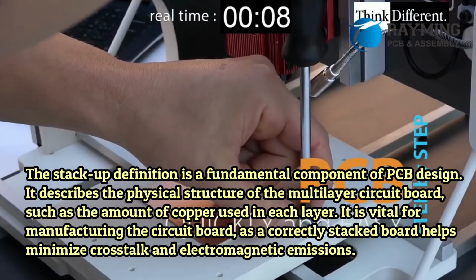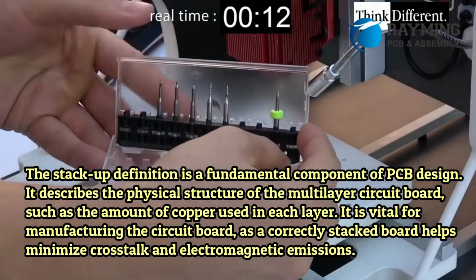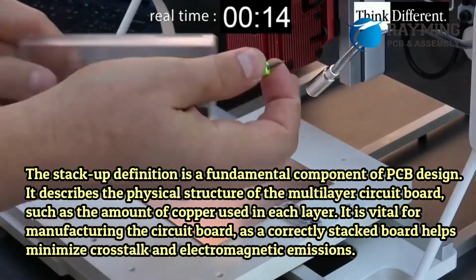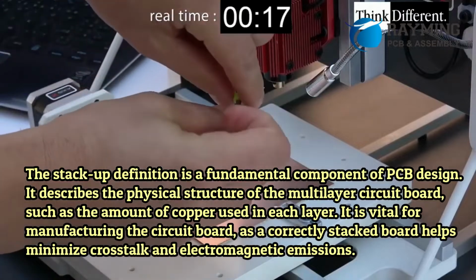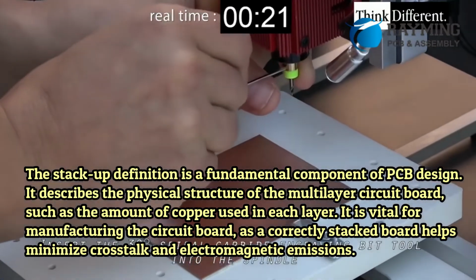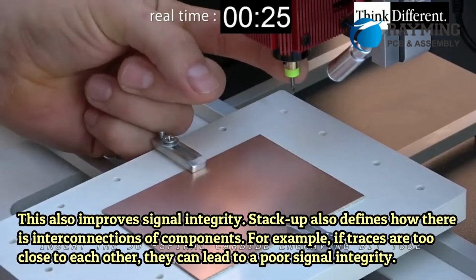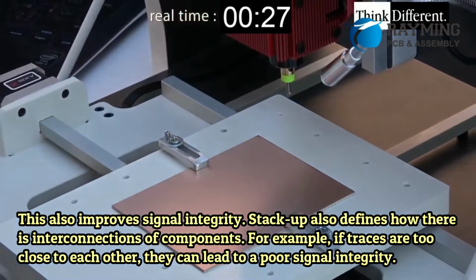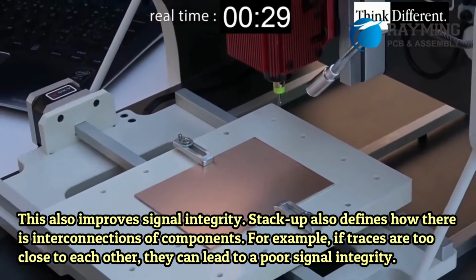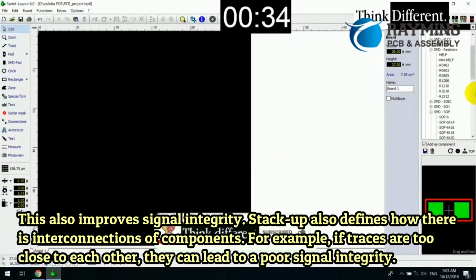It describes the physical structure of the multi-layer circuit board, such as the amount of copper used in each layer. It is vital for manufacturing the circuit board, as a correctly stacked board helps minimize crosstalk and electromagnetic emissions. This also improves signal integrity. Stack-up also defines how there is interconnections of components. For example, if traces are too close to each other, they can lead to a poor signal integrity.